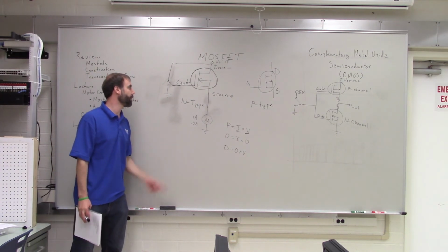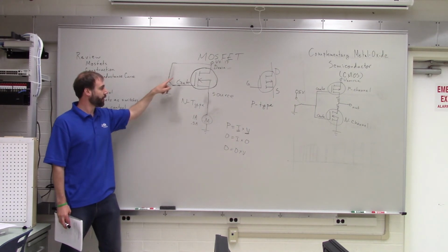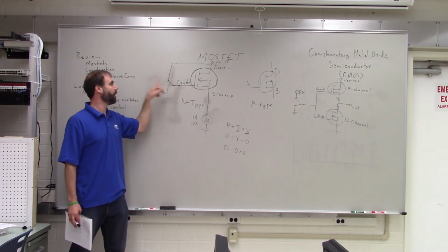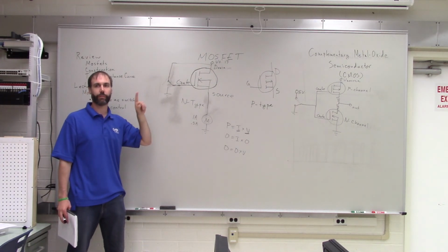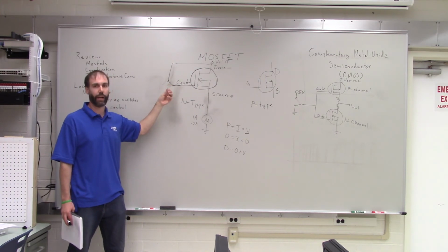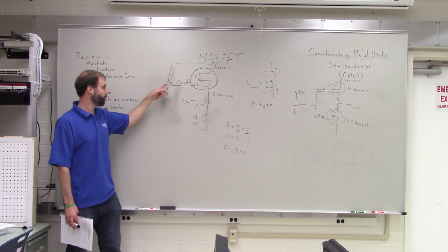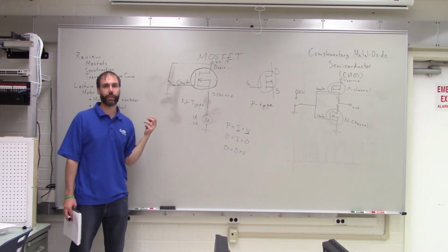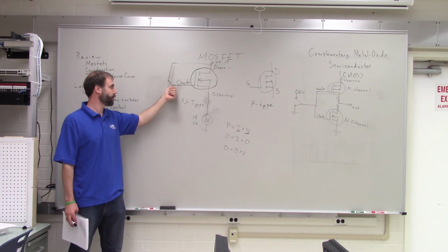And what you'll probably notice is that when you plug it into the power, the motor turns on, and then when you unplug it from the power and it's floating, the motor is going to stay on, okay? Because there's nothing that has discharged that little amount of electricity that was still on the gate. When you plug it into the ground, the motor is going to stop. But then when you unplug it from the ground, the motor is still going to stay off because, again, you don't have anything to change that state.